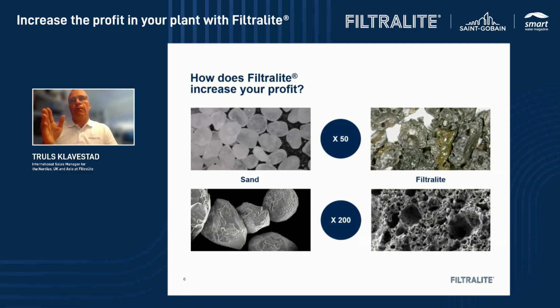If you compare with Filtralite on the right side, you see that Filtralite has a high porosity, and you can also see the sizes of the grains. All of them are different. So they are packed in a completely different way than sand, which means that you can store much more suspended solids between the Filtralite particles, but also in the pores.